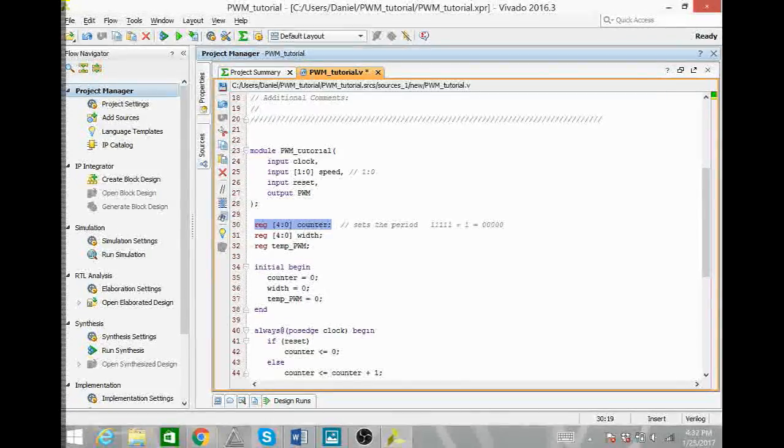Since the counter only has 5 bits, once the counter is full, once it has the value of 31, we know that if we add 1, it resets all the bits back to 0. The result would be a 1 followed by 5 zeros, but since we only have a 5-bit number, we only evaluate these 5 bits, and that 1 disappears.